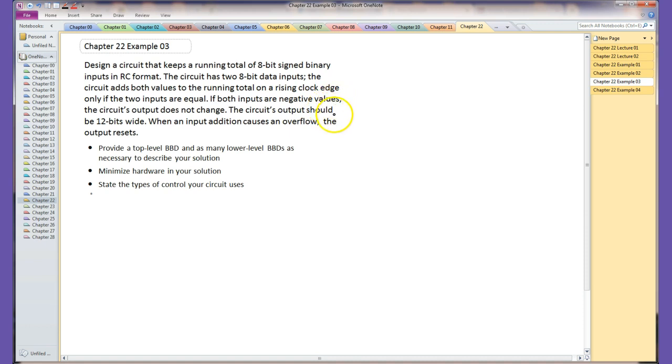There are two approaches to this circuit, and I'm going to take the dumb guy approach. Sometimes we add the summation and sometimes we don't on a clock edge, but that's not really the way to look at it. The easier way is to add the number when we need to and add a 0 when we're not supposed to add the number, and doing that simplifies the circuit. Adding 0 is essentially not adding. We'll take advantage of that when we do this problem. You'll see that come up a little bit later.